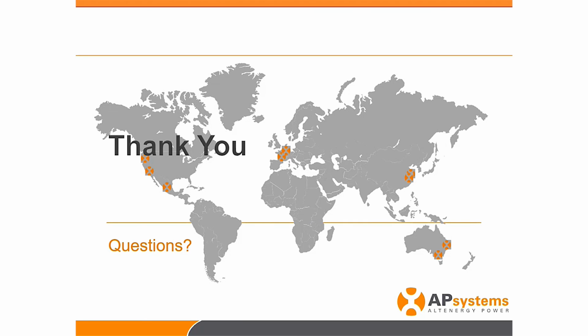Yeah, if I can ask a question. Yeah, go for it. It happens sometimes we have a unit which is not responding. So let's say, for example, a YC600 or even a DS3L unit has both channels off. So what we do is we go there and we switch it with a new one and it comes back on. The question is, can it happen sometimes that it's only a matter of it shut down and maybe we could turn it on or we could do something to get it back on the system? Can we do something before we go and switch it?